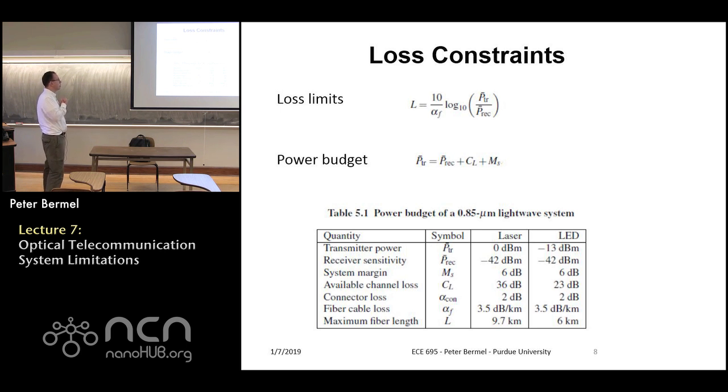So this is actually telling you that in many cases, increasing power by a factor of 2 does not increase your range tremendously. It's on the order of log base 10 of 2, which is maybe 0.3 or less. So it's pretty small. And then the other thing, of course, is that there are different channel losses as well as system variability.